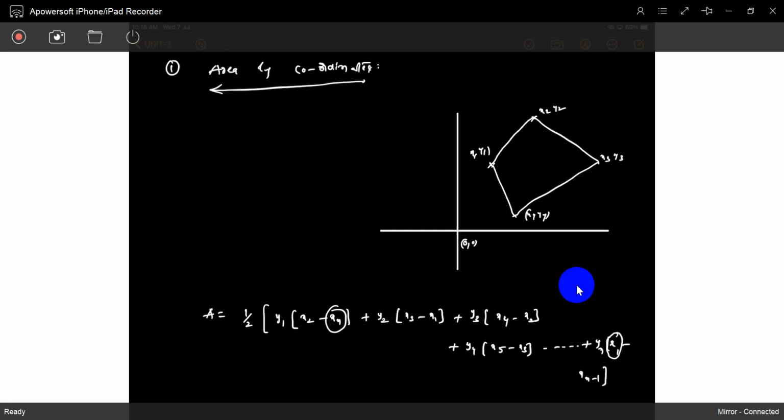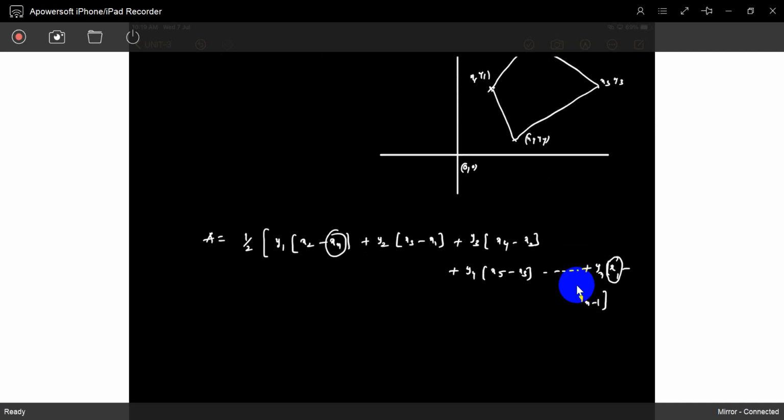It's just mathematics. So like this we can calculate the area if you know the coordinates. So how can we know the coordinates? I already said, if you're using the GPS survey or total station survey, you have to identify each point as coordinates from the fixed reference. Then we note the coordinates of every point or control point. If you know the control points' coordinates, then you can easily calculate it. No problem. I will solve one problem.